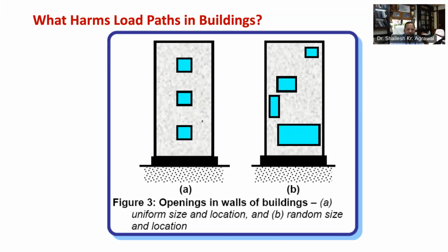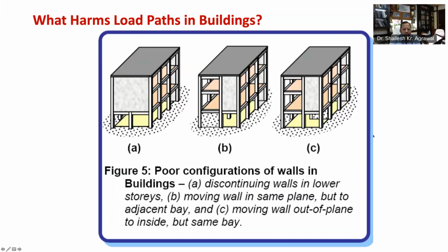Design codes give special emphasis in design and detailing of walls between openings so as to reduce negative effects of openings and ensure desirable ductile behavior of buildings with shear walls. The other departure could be the discontinuity, out of plane offsets in lower elevations. This, let me explain through this figure.